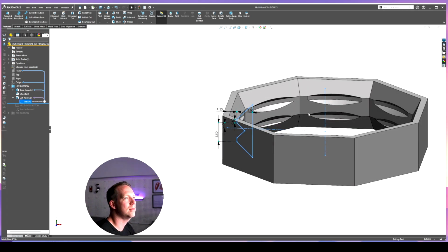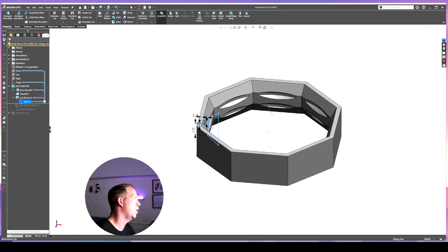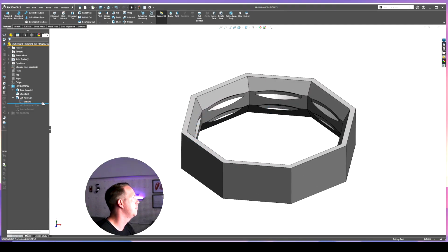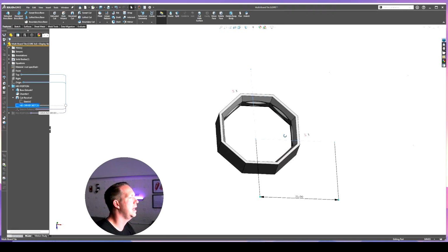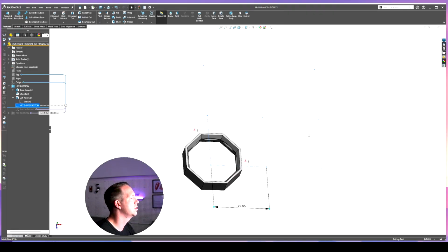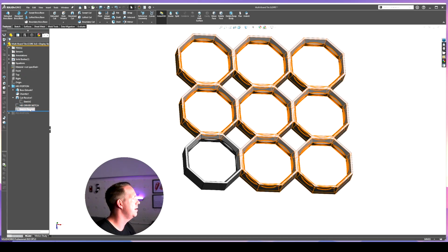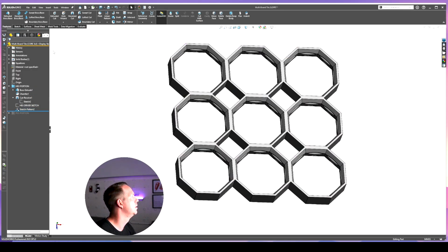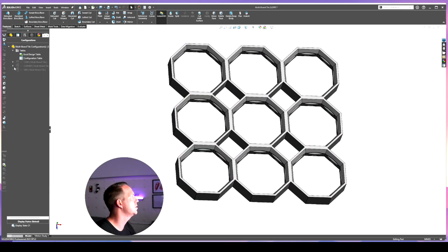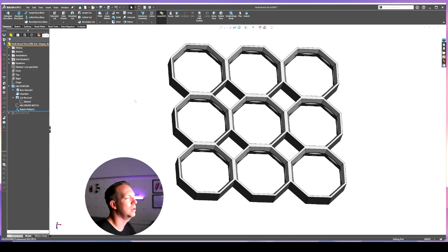1.25 being the only one that's a bit off round, but 1 1/4, I'm happy with that. I've then created a sketch, and you can see it's driven by some equations. The X and Y dimensions, or the X and Y instances, are driven by some equations. And then there's a sketch pattern feature, and this pattern, the example that I'm in here, is the core tile that is a 3x3 size. We'll have a look at that equations table in a minute.